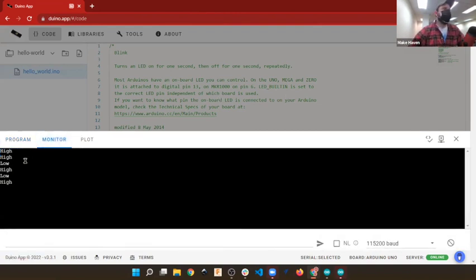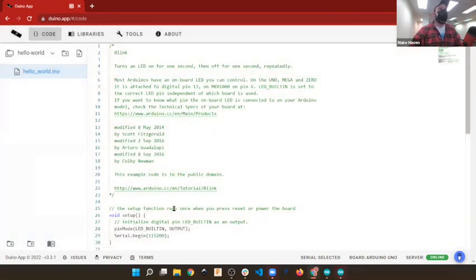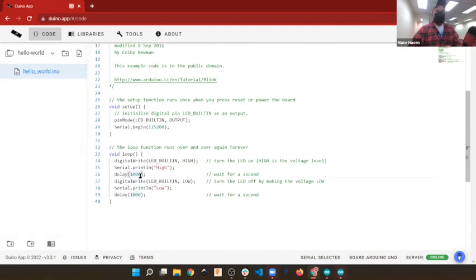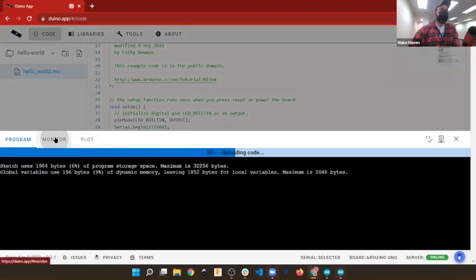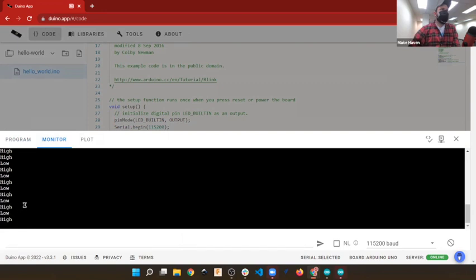And if I go to the serial monitor, I'm getting back information. So on the actual Arduino, it's blinking an LED, it's blinking a light, which is pretty cool. But it is telling me that it's connected by giving me feedback here. And so there's plenty of logistics, but it can be that quick to change things. And if I want this to happen faster, it's going to be a little nuanced, a little hard to tell, but this delay is delay for a whole second. If I just change it to 100, that's 1/10 of a second. And if I do this, you should see that the highs and lows come back in a lot faster. So just a little bit of futzing around with the code, and now you're able to make some adjustments and really see how this works.